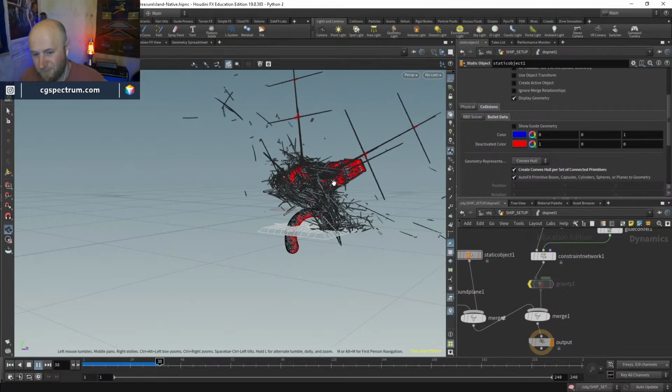Now here's where I'm going to ditch this gravity, and I'm going to put a pop force down, because this will allow me to create custom gravity conditions. And what you can do as an activation thing is turn on Vex and do -9.8 up here in the force. And then put an if statement down.